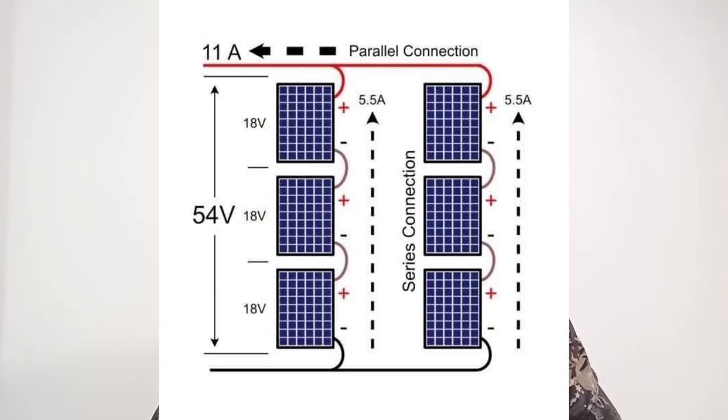But in a low voltage charge controller, it is easier to skip a string because most of the panel connections will be in parallel. So if you have parallel and series connections all together, you might do your series, and when you are doing the parallel, you will forget to connect one string of panels, which will reduce the power output you're supposed to get from your solar panels. And you might not notice when you are on the roof until you connect the solar panel array to your inverter or charge controller. Therefore, it is easy to skip a string in a low voltage charge controller.